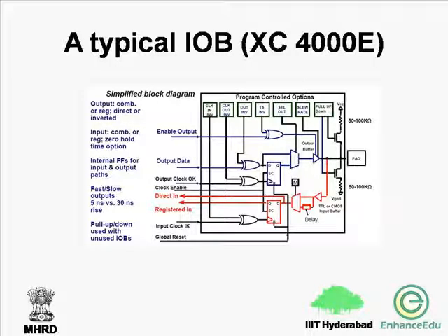So with respect to the FPGA chip, mind you, the same pin can be used for both input as well as output purposes, but in most cases we get the chip as a part of the board, and because of the connectivity of the board, either the pin is connected to some input device or connected to some output device. So the board basically restricts the specific FPGA pin to be used as an input pin or an output pin.